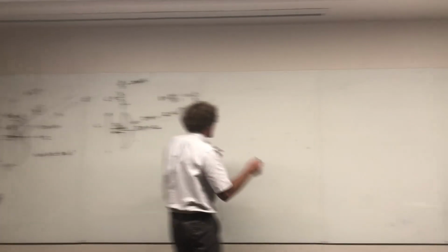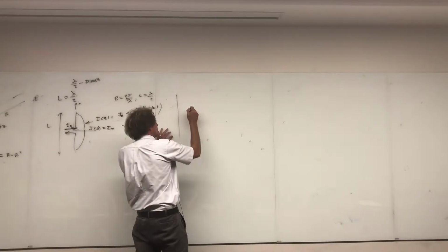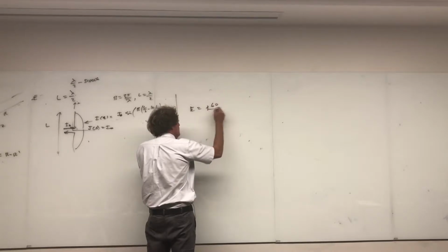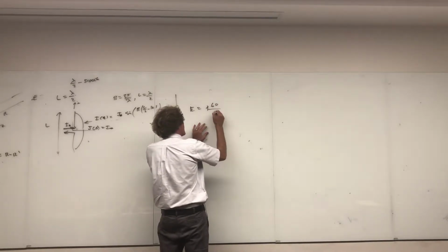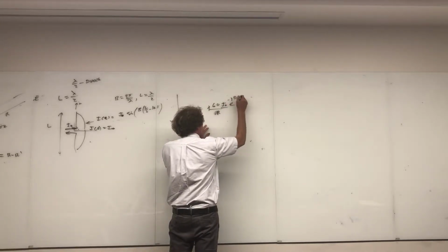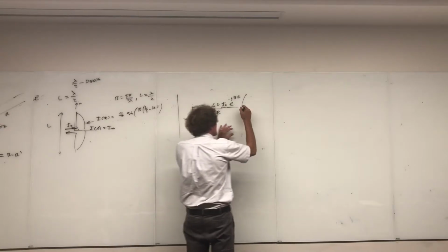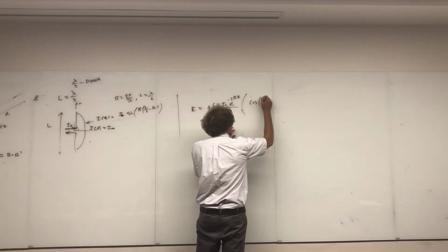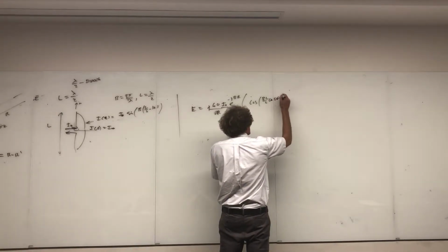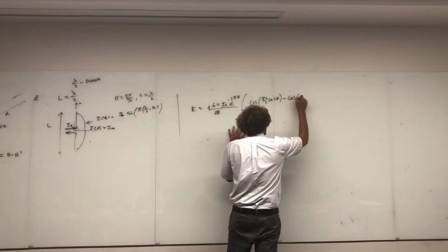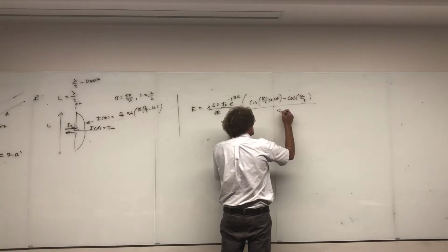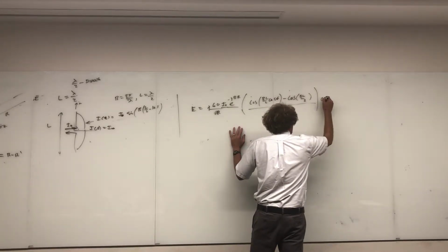Second thing that you realize is the antenna pattern. Remember, the E field in general is equal to j60 over R, times I naught, e to the minus j beta R, and then it's times cosine of beta L over 2 cosine of theta, minus cosine of beta L over 2, all over sine of theta, in the a theta direction.